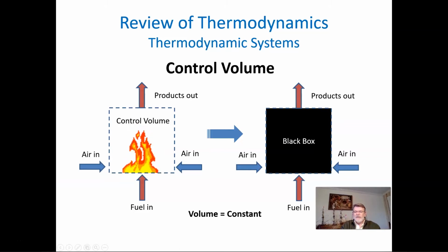But so it's kind of like where we actually are doing the combustion from 2 to 3 on that diesel cycle, right? You remember? From 2 to 3. You've got a momentary non-changing volume, remember? So what you're doing here, you're putting product in and air coming in, fuel in, and you get some product out.